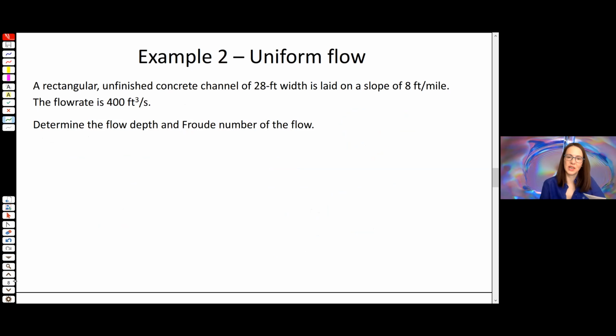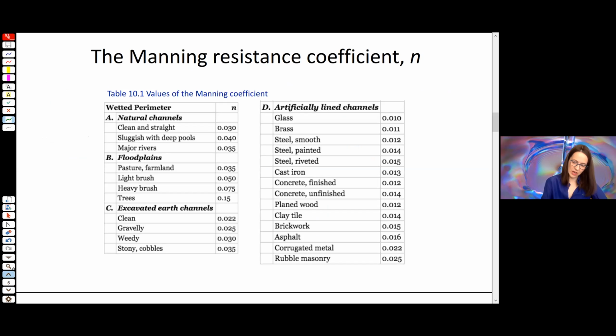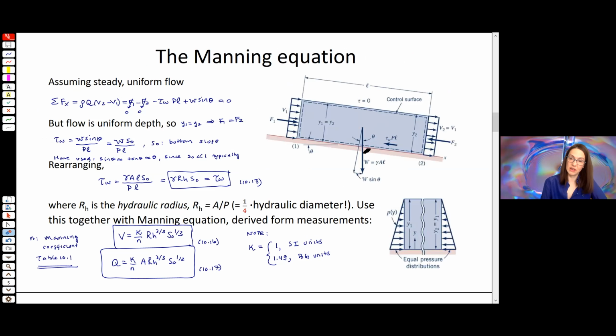Okay, so now similar example. All right, do you have a question? When does the slope approximation fail? Basically, when the small angle approximation fails. So when you can no longer say that sine of theta, so what's theta again? Right, going back to this figure, theta is your slope, basically. It's a measure of your slope. So when you can no longer say that sine of theta is approximately equal to tan of theta is approximately equal to theta, then it fails. And so rule of thumb as engineers, we usually say that's a theta of 10 degrees, something like that, right?